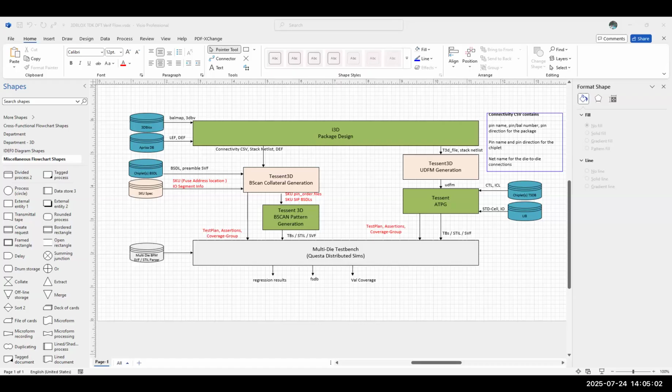All right, Bala, did I catch that correctly? Right. So this is the fuse ROM address location, which corresponds to a particular PHY IP instance. Okay, so I think the first baby step is to define a fuse. What does that mean? How do we identify a fuse, together with its address? And then associate those with PHYs and say, here's a segment, and for this segment, that fuse at address X needs to have value Y.